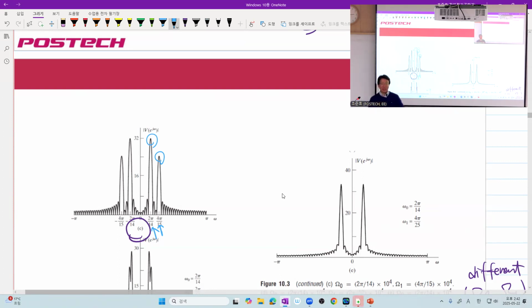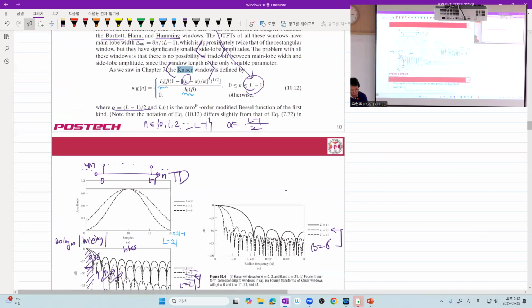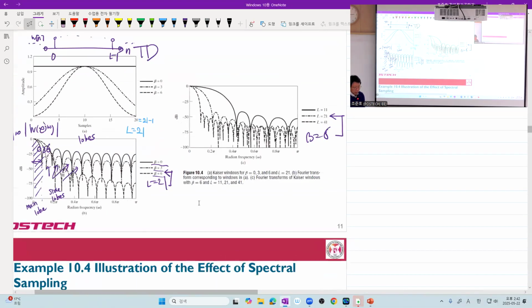So they developed some interesting filters, like here is the main lobe, and the side lobes have almost the same amplitude. And as you see here, there it is. When you have a Kaiser window, right? Since this is more rectangular, you have around 20 dB per decade type thing. And here it's slightly decreasing. But some filters really have some main lobe and of course side lobes, but their peaks are almost the same.